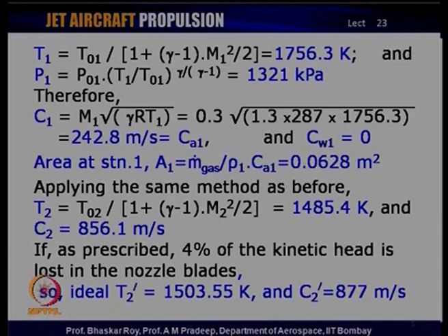Now, this is something we have discussed before in our lecture, that through the nozzle, because of the real flow situation, the actual velocity C 2 is often a little less than what could have been the ideal velocity C 2 prime. Now, this change from real to ideal is quite often a situation that happens, because at the end of the nozzle you are trying to achieve a sonic velocity. Sometimes, as we see in this particular problem, you are trying to achieve a slightly supersonic velocity.